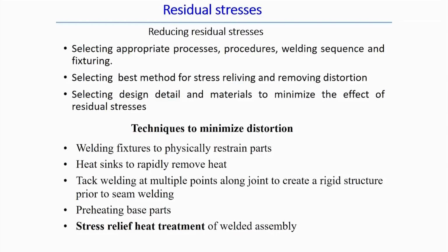But one important thing in the analysis, or maybe direction of the work, in the case of the welding process, is the measurement of the residual stress and how to reduce it, because residual stress impacts the life of the weld joint. Therefore, it is very important to assess the amount of residual stress generated during the welding process.